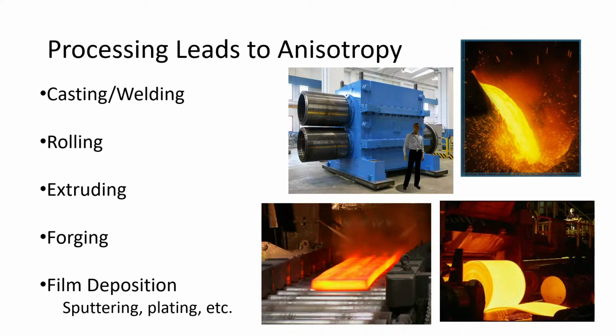Then it's not a Schmid behavior; you get dislocations pinned by the particles or the solutes, and you get a different type of texture evolution. So there are a lot of unanswered questions, a lot of specific details that we know about, but also a lot of unanswered questions on how exactly texture evolves in specific alloys, chemical composition dependence, as well as geometric dependence.